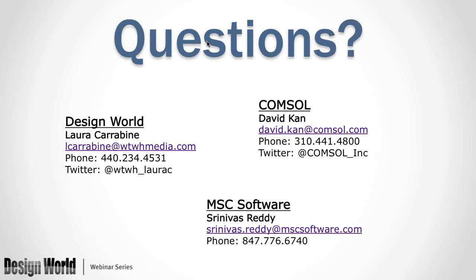This is true for anything, including non-mechanical models. For mechanical models with the load, you'd put in whatever those load steps might be. If COMSOL doesn't converge, meaning you don't get an answer that's close to being right, then COMSOL will automatically put in intermediate load steps to get you to the right answer. That's how COMSOL works with the parametric solver.